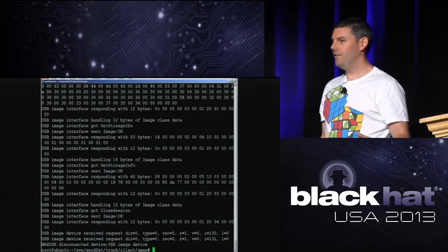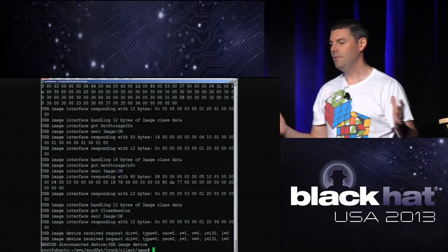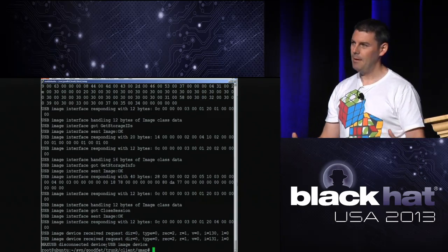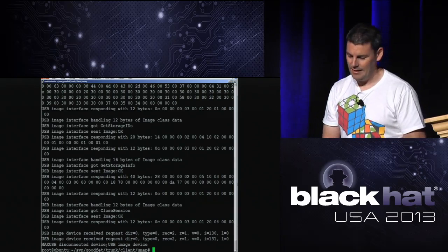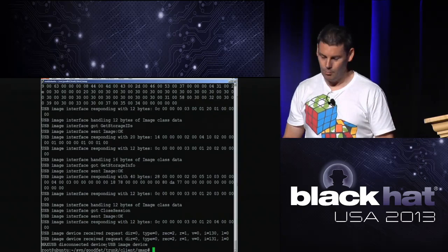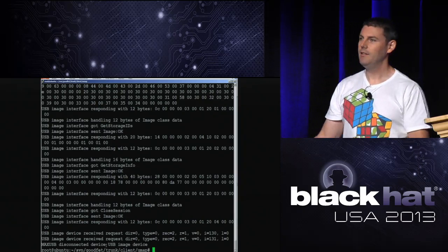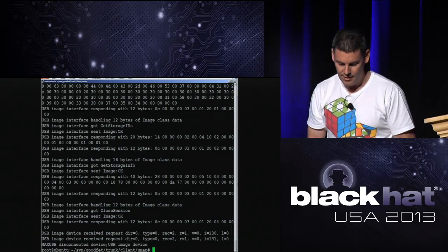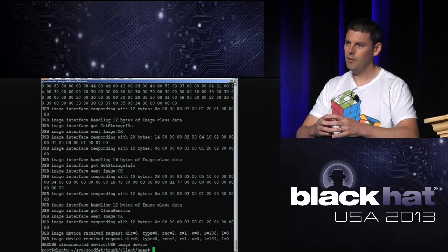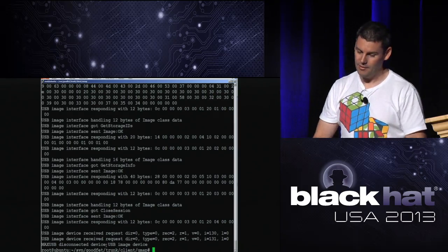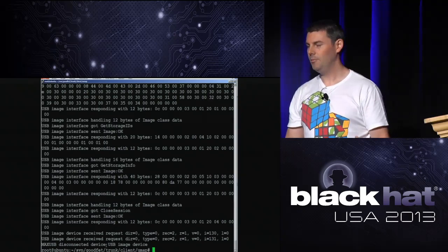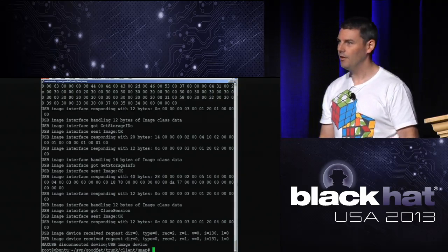And I've mentioned fuzzing a couple of times. I've done quite a bit of USB fuzzing in the past, and this new capability that FaceDancer has allowed me to have provides the capability to do much more comprehensive fuzzing now. So you identify what classes are supported, and then, rather than the mutation-based fuzzing that I've done in the past, you can look at the spec and implement all your fuzz test cases based on the spec for the class of device that you want to fuzz.